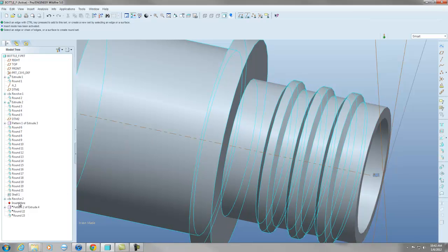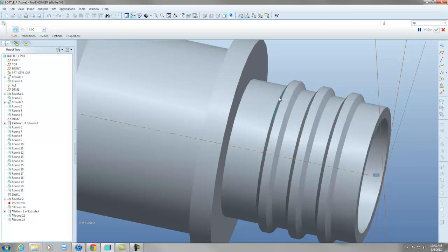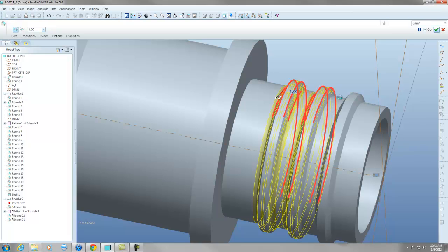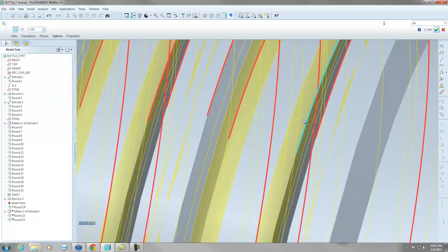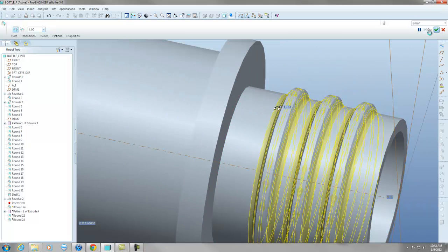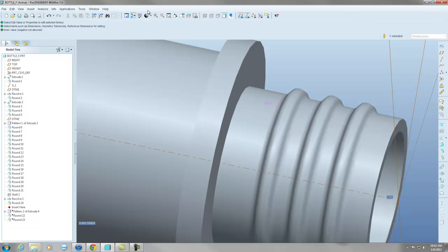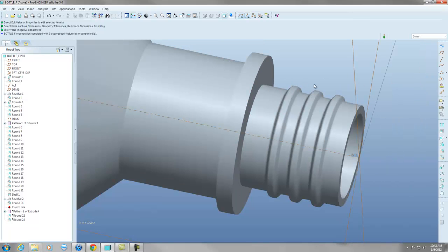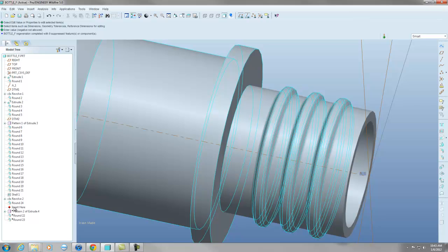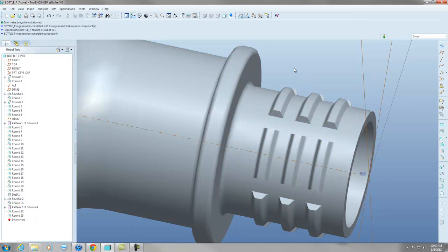If you move your insert here in the tree up to where you did your revolve, just after it, you can blend these ones right now, and then you don't have to put in 1,000 blends later. Made that 0.5.